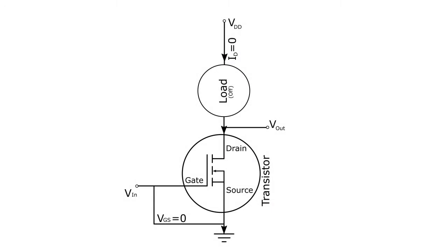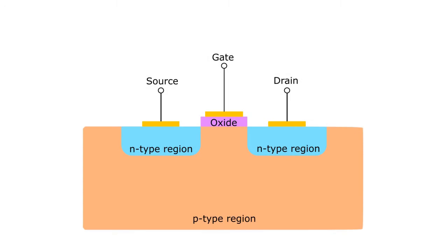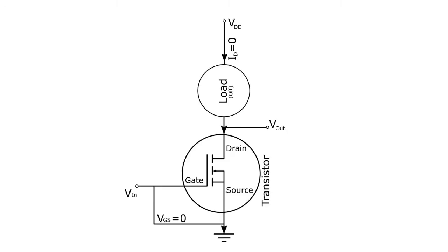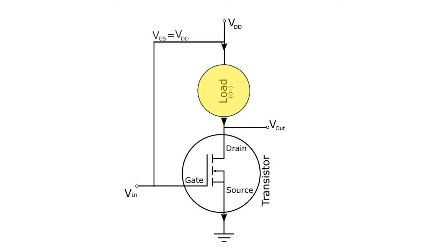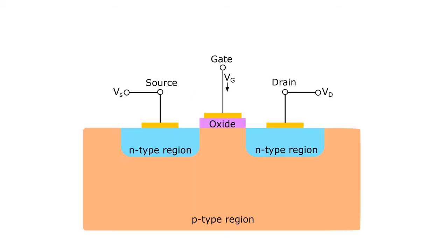A transistor is a semiconductor device used to amplify or switch electronic signals. It is composed of semiconductor material with 3 terminals and is connected to an external circuit. A voltage or current applied to one terminal, the gate, controls the current through another pair of terminals, the source and drain. A field effect transistor uses an electric field at the gate to control the flow of current rather than directly injecting current at the gate.